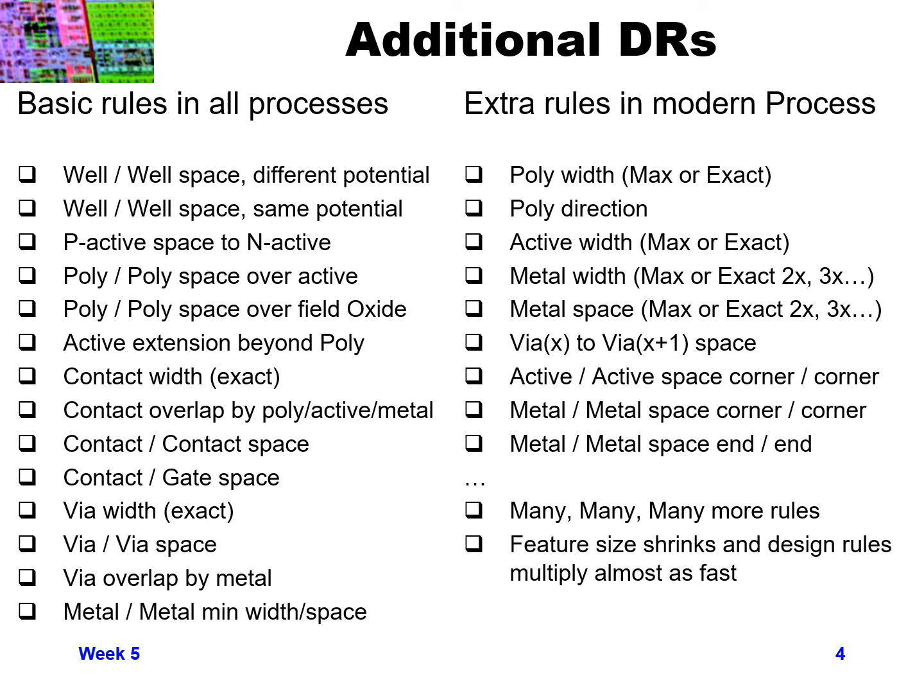In some cases it has to do with planarization. Your chemical mechanical polish maybe isn't quite good enough, and so you have some irregularities where the existing vias are, and so you need to space out the via to the next layer by a little bit of a distance, so that there are not going to be problems due to planarization.